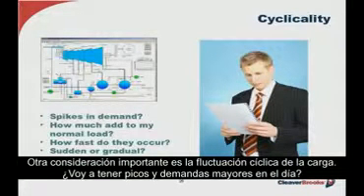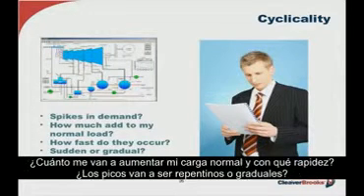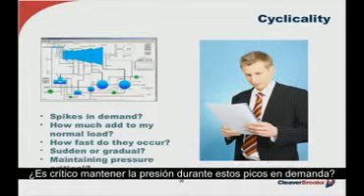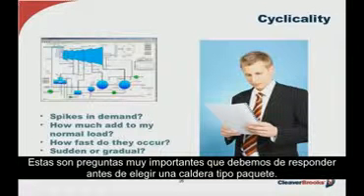Next major consideration point is the cyclicality of my load. Will I have certain spikes in demand throughout the day? How much will they add to my normal load, and how fast will they occur? Will they be sudden or gradual builds? Is maintaining a certain steam pressure critical for the process during these spikes in demand? These are all very important questions to have answered before a particular boiler package is selected.